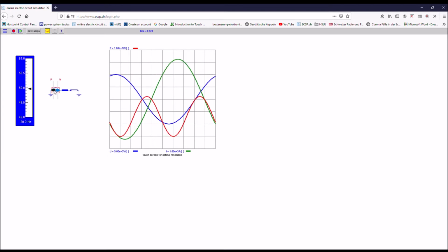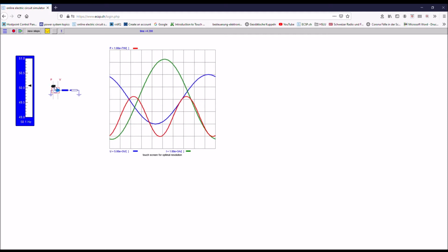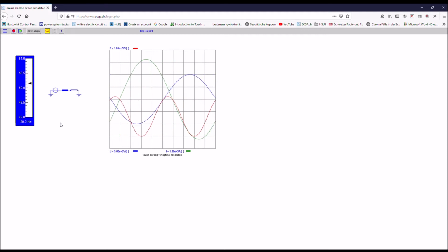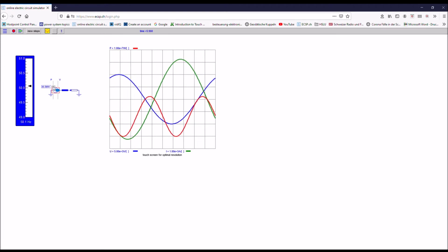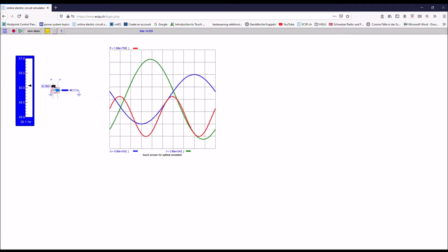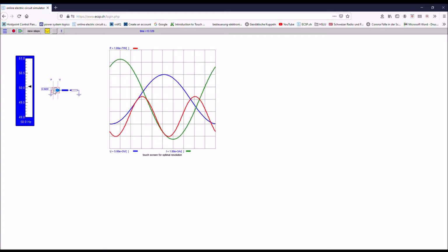The power output will be controlled accordingly. So you can see, even if I push my power output, the real power delivered from the source to the load is limited by the frequency control. And this is exactly what also happens in a real power generation station. So the droop helps to keep the balance between generation and load. And by the way, the power output slider here adapts the torque applied to the generator. So it's kind of a torque regulator.